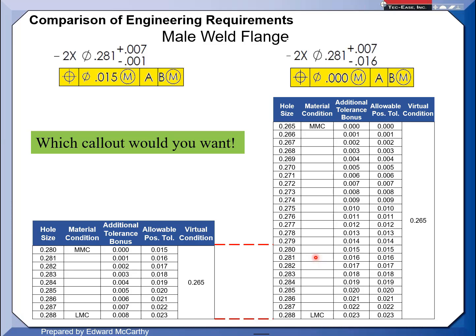So again, I've definitely given my manufacturing engineers more control of their destiny. Hopefully they don't blindly grab this tool size here, because if they blow the hole bigger, it's a paperweight. Hopefully they do it based on process capability, just FYI.